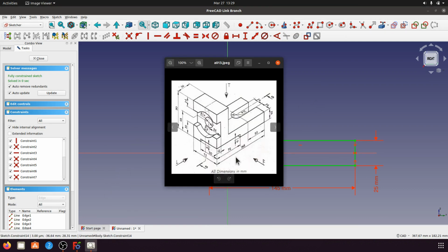Okay, so we can check again. To create this cut, we can create it now. For the dimension, from this edge 24, and then from the bottom 30 millimeter. So this cut dimension is 90 millimeter minus 30, 60, minus 24, 36, so 24 by 36, and for the depth 12 millimeter.